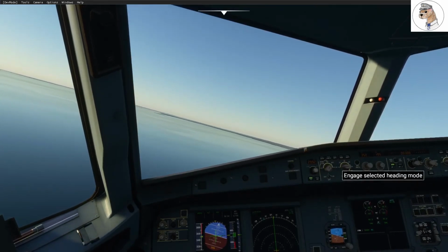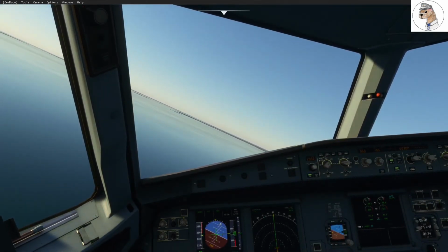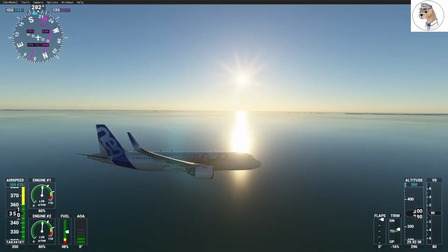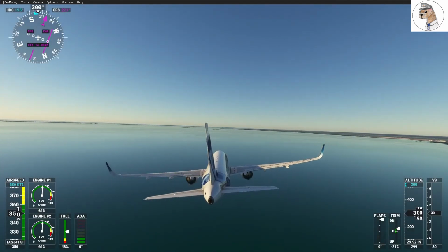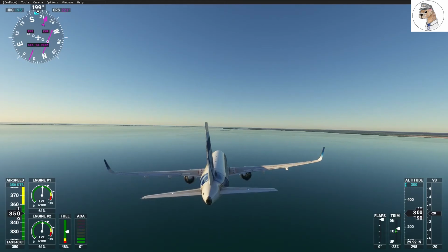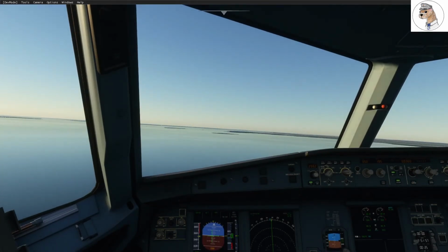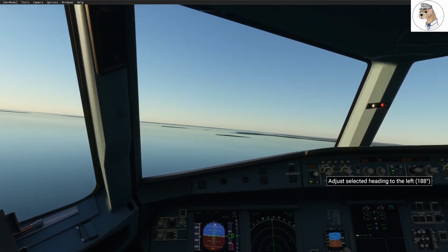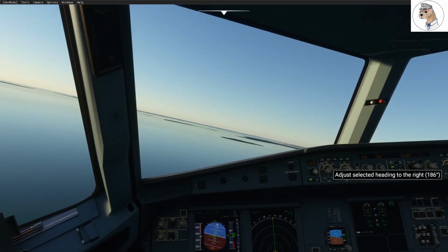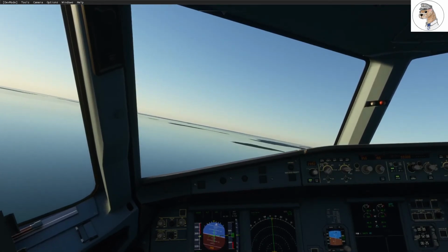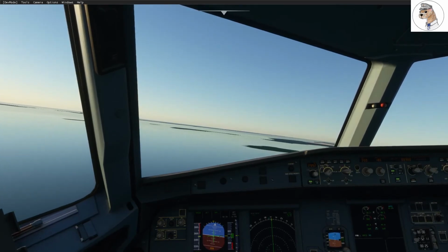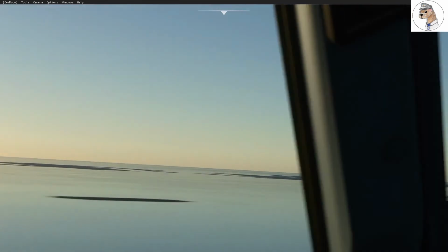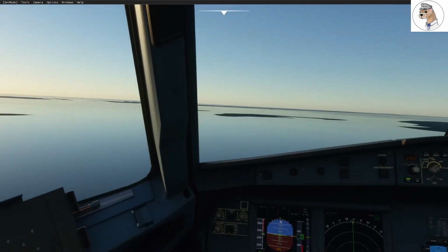So let's talk about what happens if a BMC fails. Now, on the whole, this isn't that much of an issue unless we have a problem on that side of the aircraft. The other BMC will monitor the overpressure, overtemperature and wing leak signals that the failed computer was monitoring. However, we will now have lost the fault light on the air conditioning panel on the overhead, as well as the associated bleed valve will not close automatically if we have a problem. So, as you can see, in terms of diagnosing a problem and the ramifications if we have one, it's just something to bear in mind.